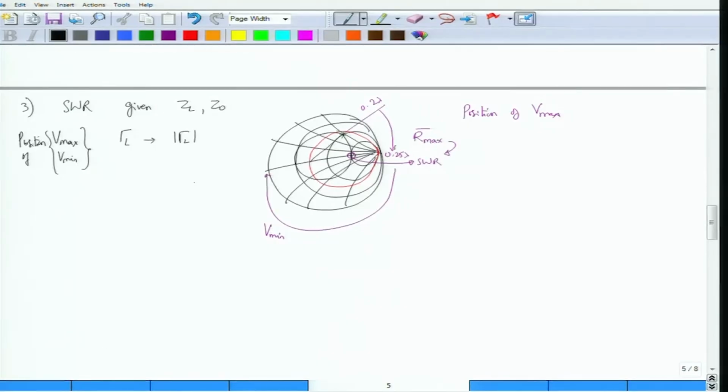So what is the position of the first maximum? As you come over here this would be the maximum that you would reach first. So the first V max would be located at 0.25 minus 0.2 lambda, which is 0.05 lambda, and if lambda is given to be say 10 centimeters, then this would be 0.05 into 10, so and so centimeters for your location of the first maxima.